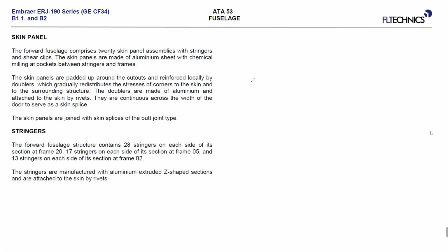when the aircraft started to be designed 100 years ago, the windows were square, and later they found that in the square windows, here on the edge, there are cracks, and with the experience in the service of the aircraft, these cracks increase and suddenly the fuselage is separated. That's why now we have rounded windows, rounded cutouts, because there is no stress here, there are no corners.